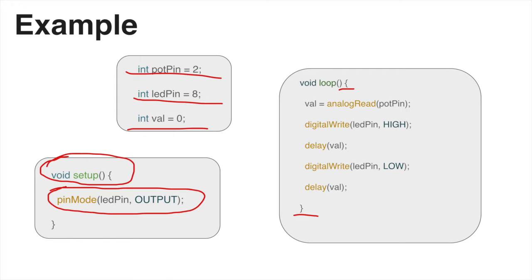All right. So we are reading the analog value from pin A2, and again, that's from a potentiometer, which is a variable resistor, which is a knob. So this value is not going to be just high or low, although it might be high if it's all the way up, but you want to think about that knob that we talked about, right? So you're going to have all these different values, all these tiny minute values, and this val could be equal to any of them.